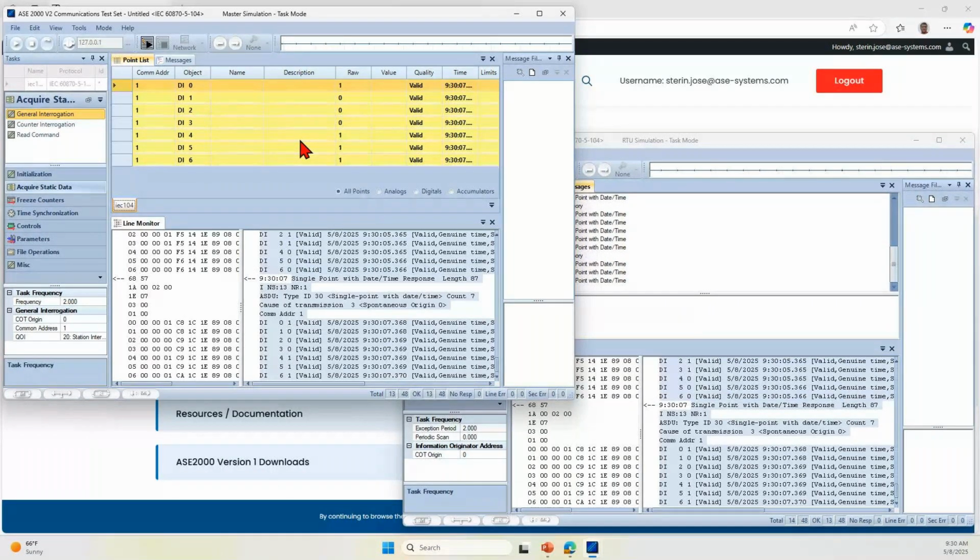The main difference here is that the communication will happen in a secured channel in case of IEC104, but in DNP3, each and every message, especially the secured messages, are appended with a hash so that the other party can verify whether it is coming from the correct source. So between 104 and DNP3, from a configuration perspective, there is not much difference.